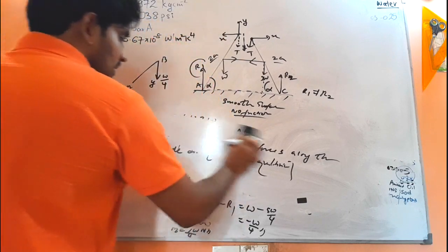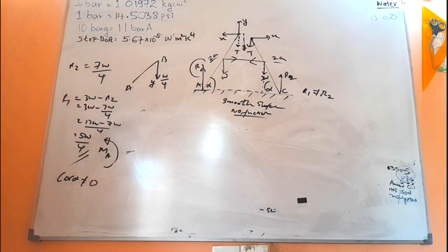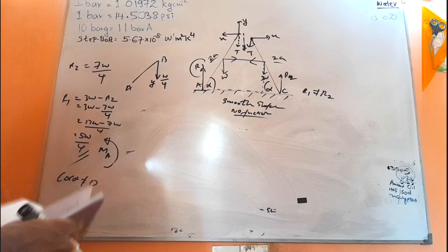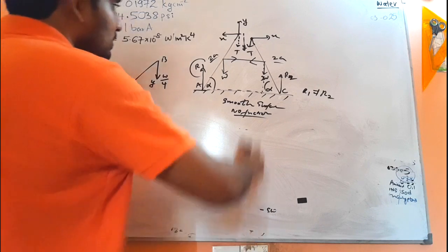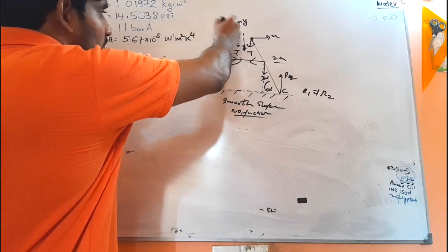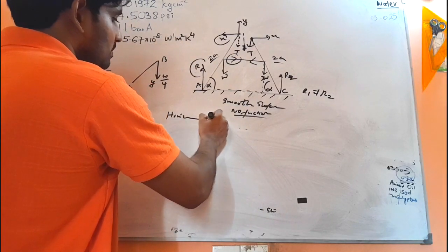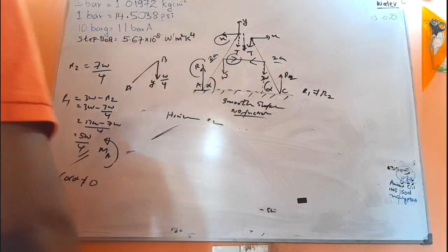So then I will erase this part again. Right. So now here the problem is, when finding the value of this force X, there is another guy. What is that guy? There is a tension, right? This tension also we don't know, this X also we don't know. Understand? That is the point. So when we consider the horizontal equilibrium for this rod AB, it will not be possible for us to calculate the value of the force X, right?